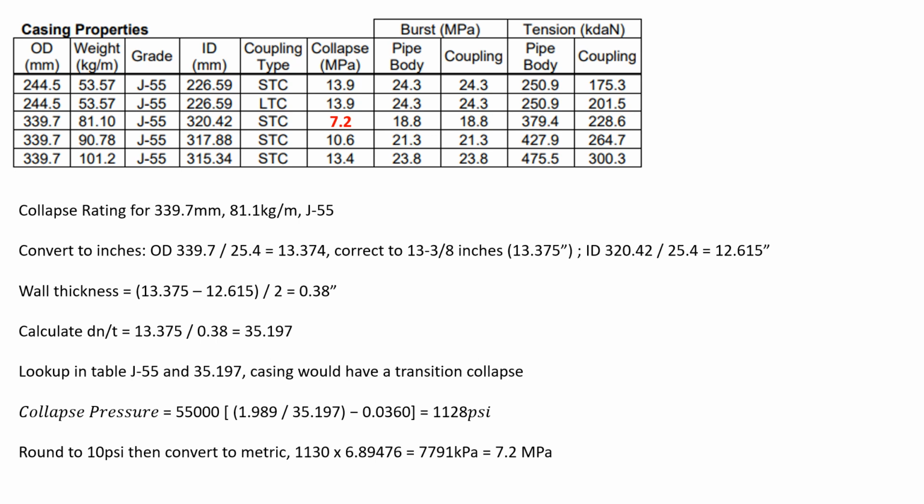Now for the collapse rating calculation, convert the diameters again to inches, correcting just the outside diameter to the nearest 1/8 of an inch.